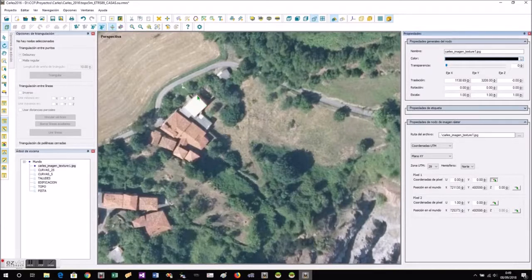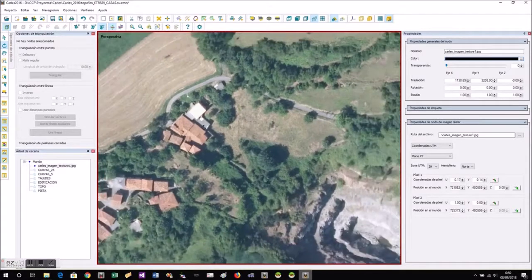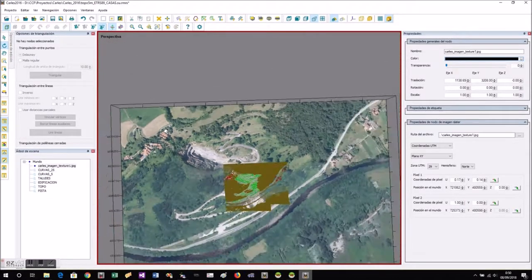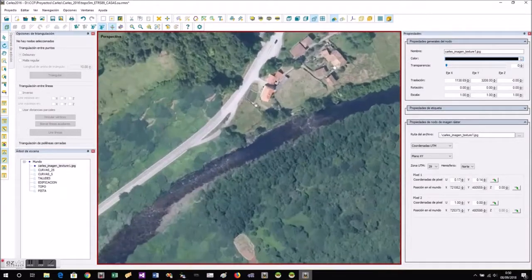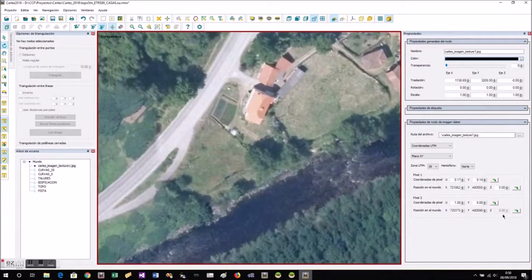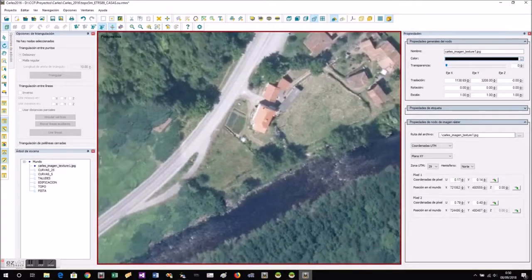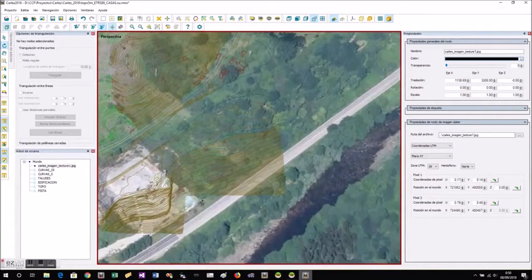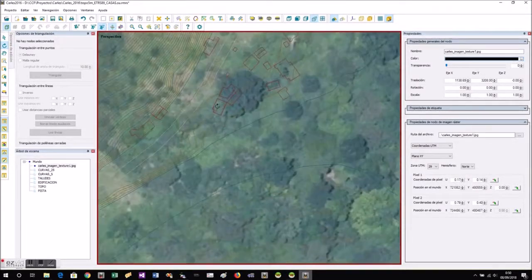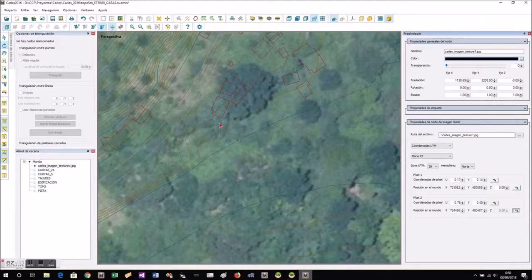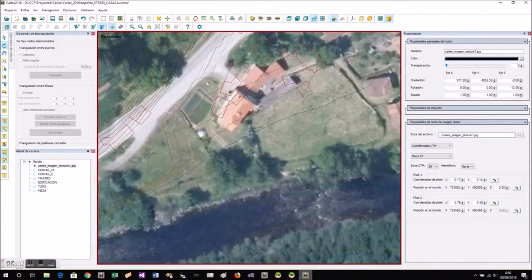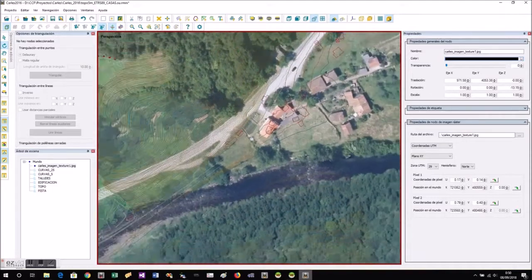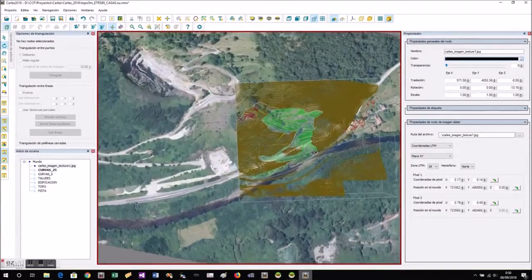When we click the image we get the georeferencing part. If we say that it is flat X and Y, as we see in this case, we have to give it 2 points in which we mark the pixel. We mark a pixel in the image, one would be a house, the other a house on the opposite side, and we say which is the corresponding coordinate in the geometry, where we place it in the corner. As we see, it has already placed it in its place.